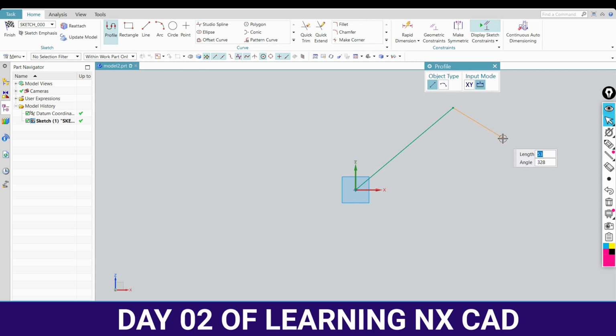It is still continuous because profile mode is on. Again, if you want a line, you can select the line, and you can complete the profile like this. If you want to escape the command, you can just press escape. After that, if you want to use another command, like line for example, you can select it and create a line here. Here also coordinate or parameter.